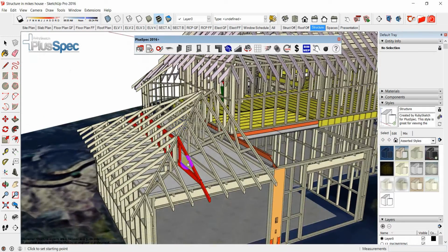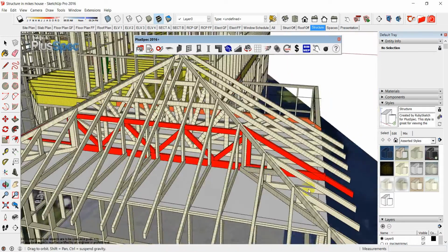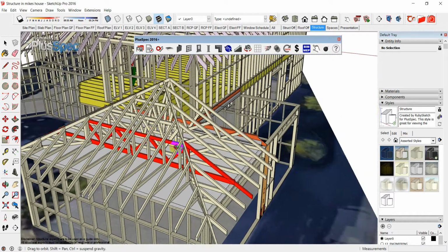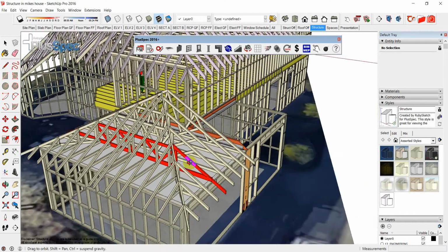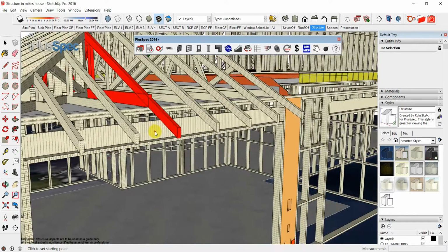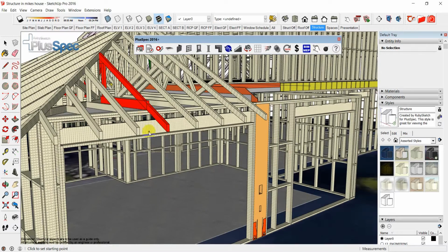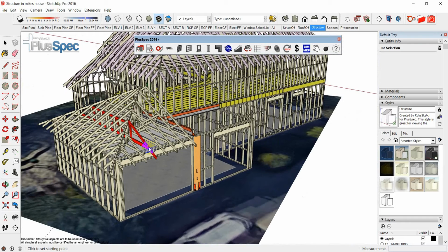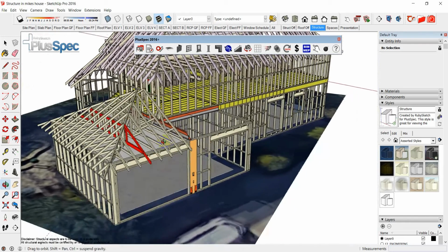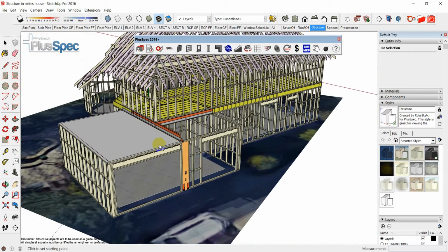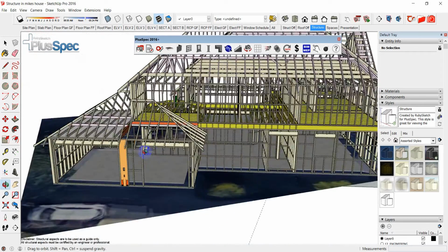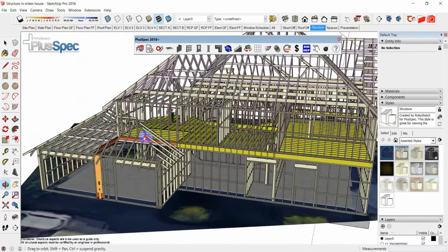It also showed me that I have a load bearing truss here, which is a girder truss, because this truss is holding these trusses as well as it's holding its weight here as a rafter, and it allows me to see, well, I might need to upgrade the size of this beam or put a steel beam in to make sure that the point load on this truss is not there. I can also change the distance of this as well. Okay. This is a pitched roof. In Texas, labor is cheap, therefore it's cheaper to do a pitched roof or a stick timber roof.